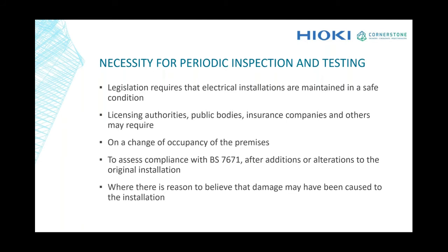This is a standard. We will discuss later about that one also. And when there is an alteration in the electrical installation, it is required to verify whether the alteration is as per standard by performing periodic inspection. And if there is any damage to the installation, for example a flood or fire breakdown, then also it's required to inspect and verify the condition.